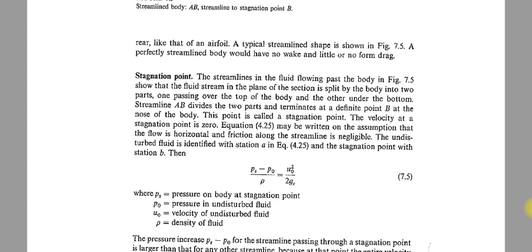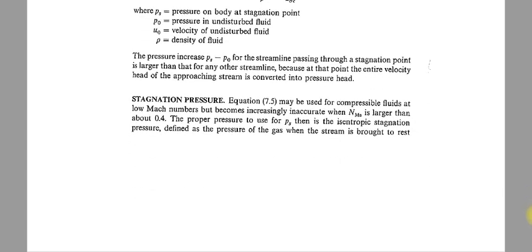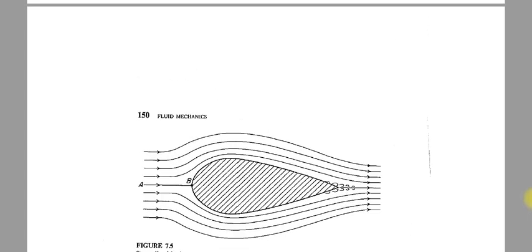We will discuss in the next class what the fluidized bed reactor and fluidization are. That is very important in reactor design. This type of flow is also useful to study the flow of slurry. If you have a solid-liquid mixture or paste transported through a pump, you can calculate how much drag force will be exerted by the fluid on the solid particles, and you can calculate the velocity of the solid particles based on that force. So these are different applications of drag force in chemical engineering.